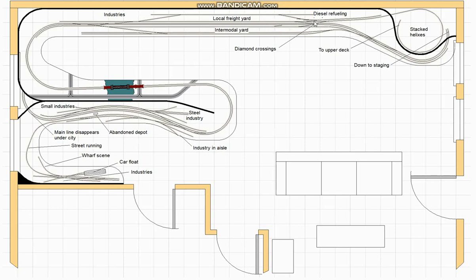But since the two outer tracks have a greater than normal track spacing from the main line, it's possible to marry a pair of number 8 turnouts at the ends, extend the turnout curve slightly, and then put a pair of 14-degree crossings over the main line. And by doing that, we save about 2 feet.